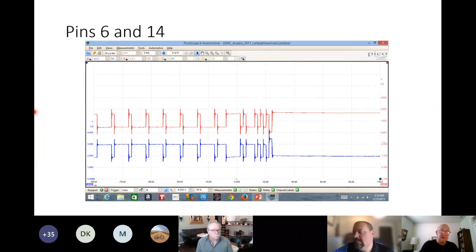When I teach this in a class, I usually borrow somebody's cell phone, and I hold two cell phones up to my ears, and I say one of them is one side, one of them is the other. And the nice thing about this is if one of these cell phones drops out, I still have the other one, which means if one of these signals disappears, this car, in theory, should start and should run. It might not run real well, and it also might not run any of the monitors. We found that in our Illinois emission groupings up here in Illinois. That's frequently, if one of the systems is down, you don't get the monitors to run, which means you don't set any DTCs, you don't set any check engine lights or anything else.